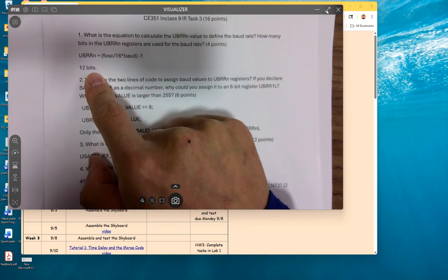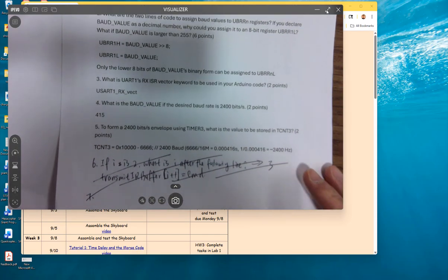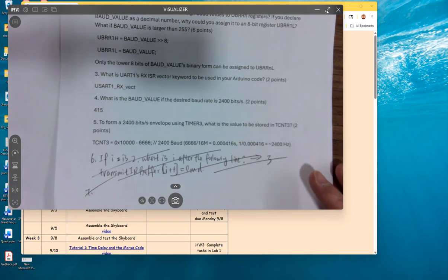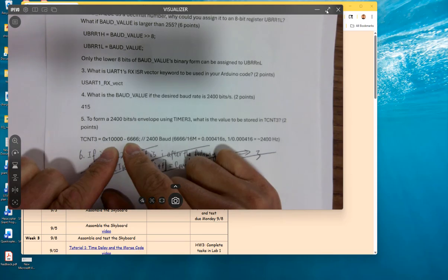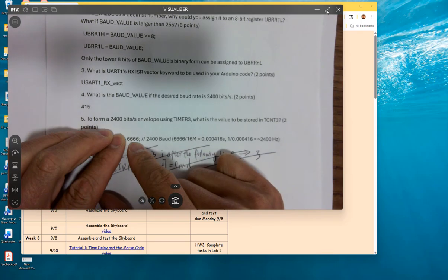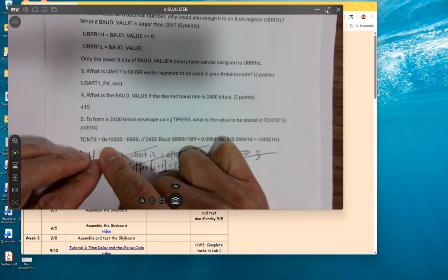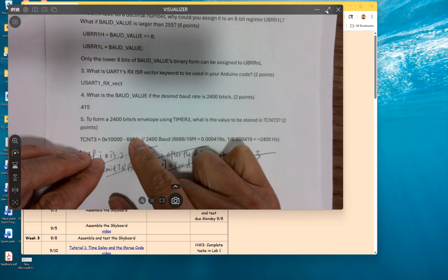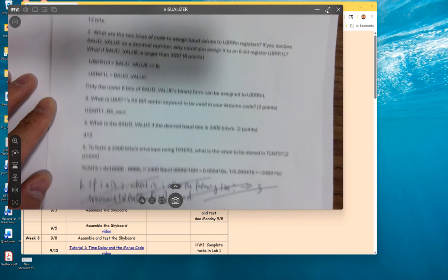So it's 12 bits. I think 80% of the guys made it right. No, actually not really anything. This one, a lot of you just directly put this number over here, but for the value to be placed in this counter register, you need to use this one minus this guy. That's the only minor issue I found. Okay, but other than that, not a big deal here.